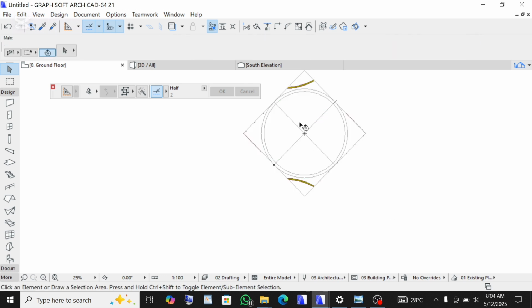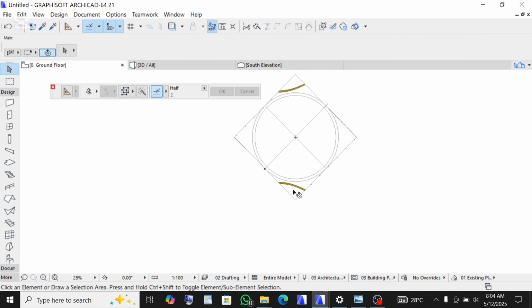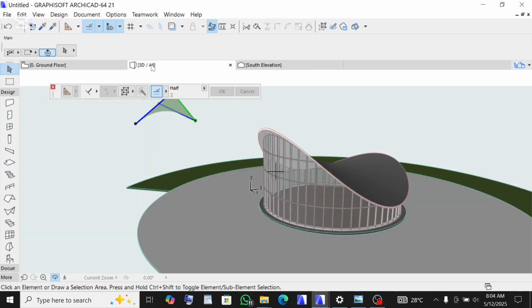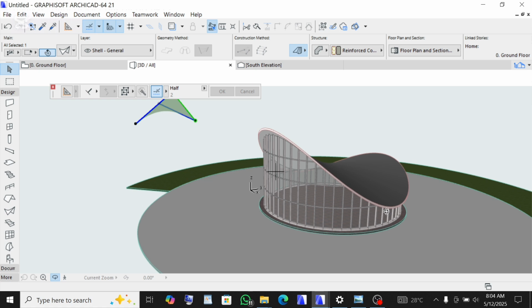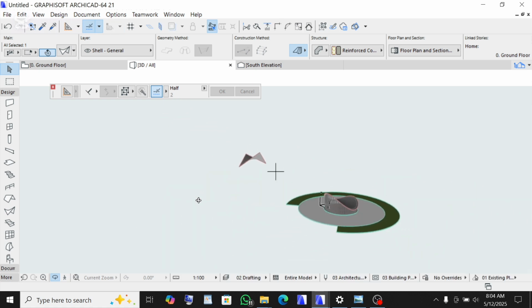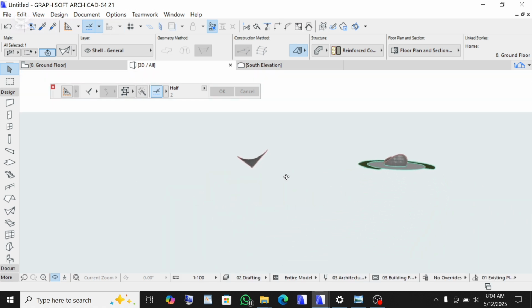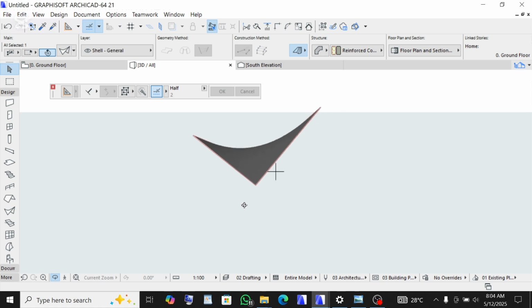One thing you should make sure of is the approach view, the place we elevated, the place we indicated 9 meters on. Make sure that part is here, is the approach view. So go to the 3D to confirm. Let's go check it. You can see it's wrong. This part is supposed to be here.